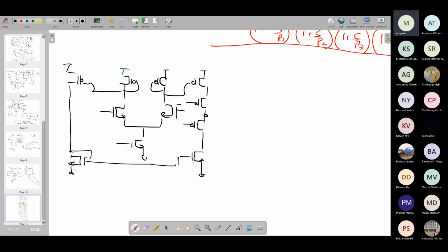So this is your positive input. This is your negative input. For the inverting gain amplifier, you put R2 by R1, and you put the input signal over here, Vin, and there is some DC signal over here. Whatever you put is treated as AC ground, generally some DC signal. So that same DC will appear here.